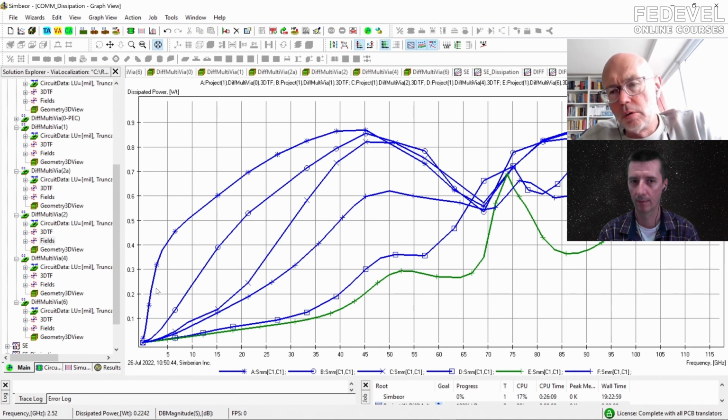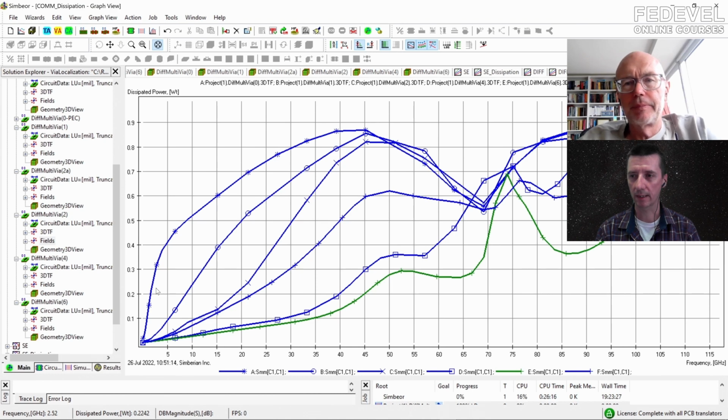If you are at lower data rate, below 10 gigabit per second, those mode conversion effects do not matter much, but when you get to like 30, 50, 100, or 224 gigabit per second, then everything matters. So a small amount of crosstalk may kill your signal with the amount of losses you can encounter along the link. So basically, I think we should explain a little bit more.